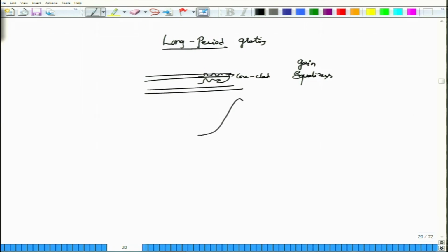We know that the erbium doped fiber amplifier has a gain cross section that looks something like this, from about 1526 to 1560 nanometer. Clearly the central one near 1550 is the one that is getting a lot of gain, but the others are not really that equal in terms of the gain. So, if you have multiple channels here, the central channel where the gain is peaking will have the higher gain, while the others will have a lower gain.